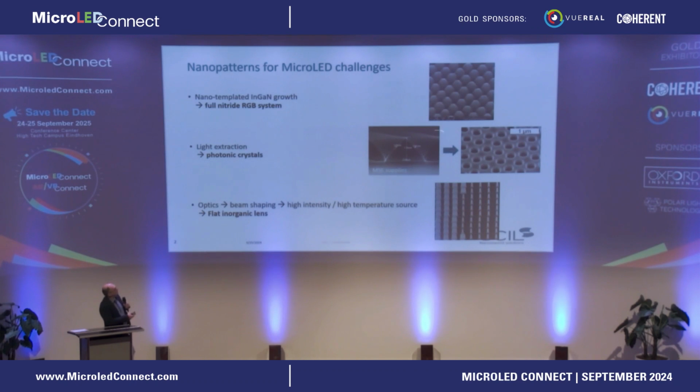Standard in LEDs, micro PSS is used, but you see that this cone is about 3 micron, so you get 1 or 1.5 cones if your LEDs get smaller. So you would like to work on photonic crystals. I'll show results from that.